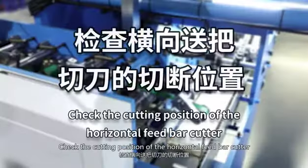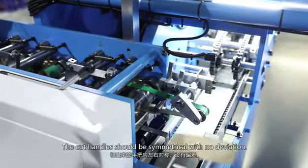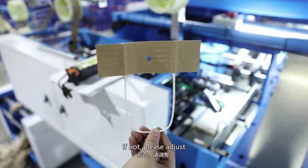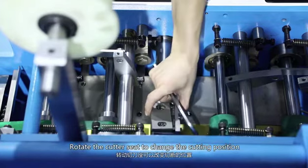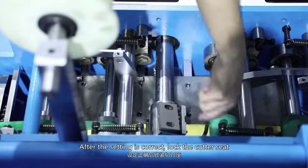Check the cutting position of the horizontal feed bar cutter. The cut handles should be symmetrical with no deviation. If not, please adjust. Loosen the fixing screws of the handle cutter seat. Rotate the cutter seat to change the cutting position. After the setting is correct, lock the cutter seat.